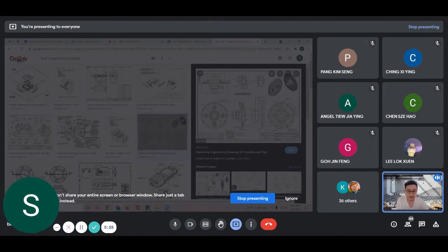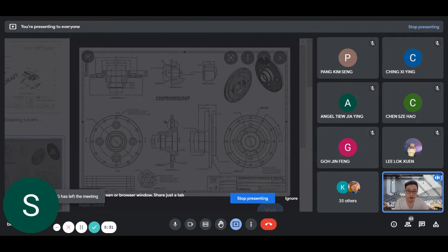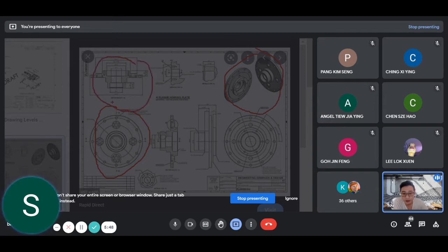Another thing, if you notice, this one is able to showcase how a drawing will look. This will be rare. What we usually have is something like this, maybe a top view, a cross section view. This is what we call a section view. If it's not clear, we can have a cut through section AA, meaning we cut through this object. So we can have different types of view on the object, and you will have all the dimensions, and then finally you have your title block.